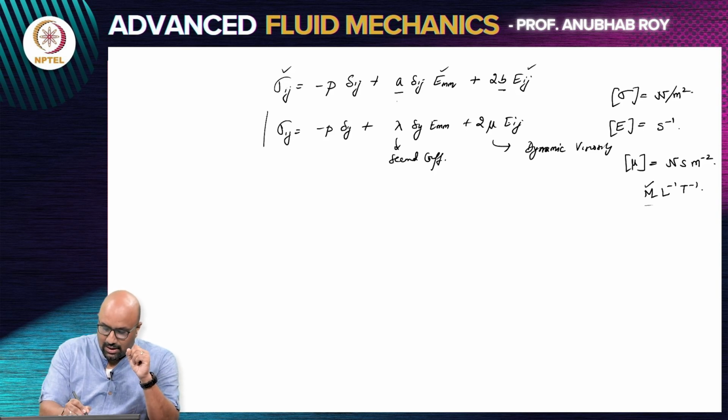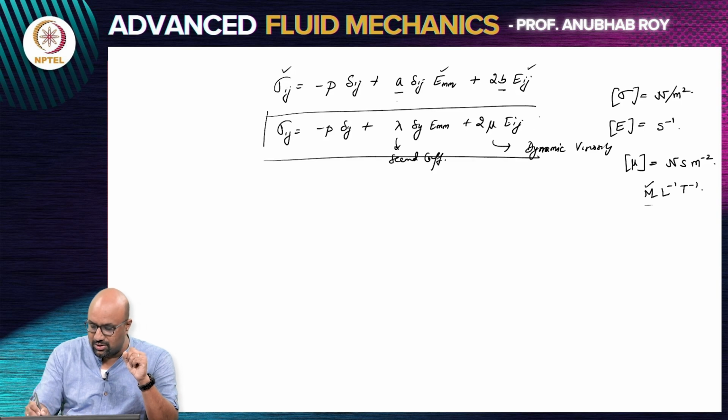So, this is the constitutive relation between stress and the rate of deformation in a Newtonian fluid. This is quite different from a conservation law. This is constitutive modeling. As you saw, at various steps we made assumptions when we arrived at this. This is not something being done from first principles. You make certain assumptions of the material.